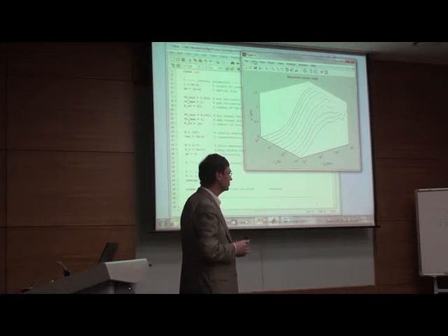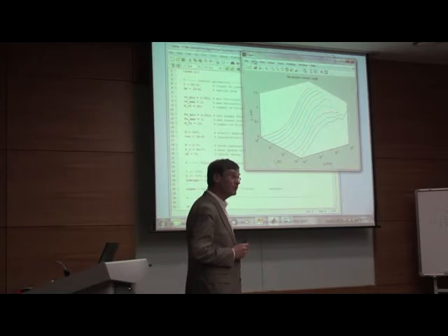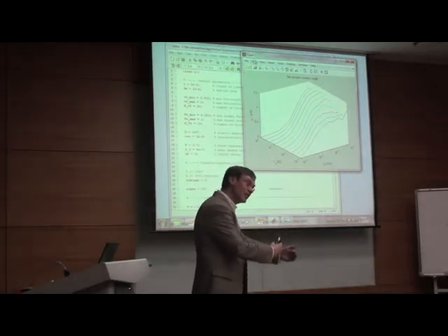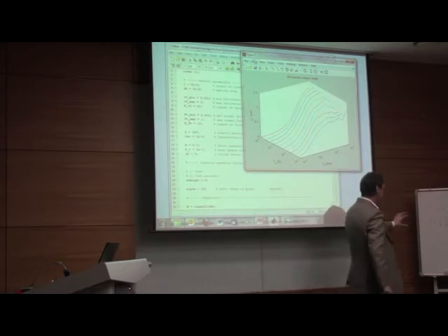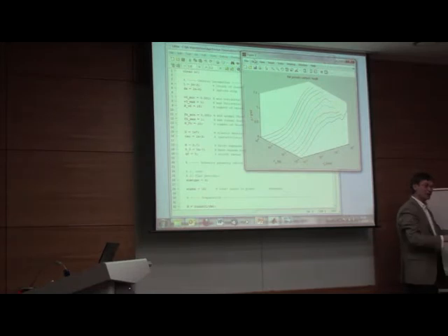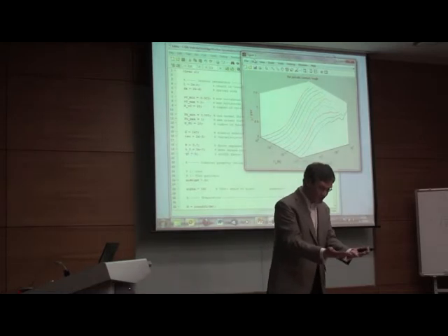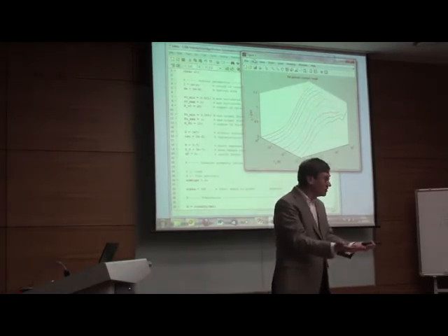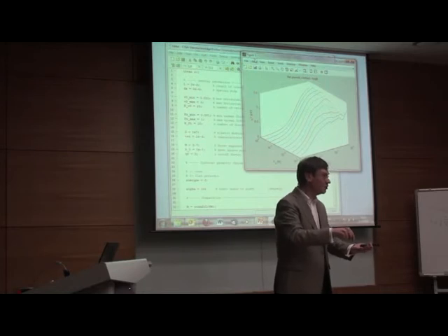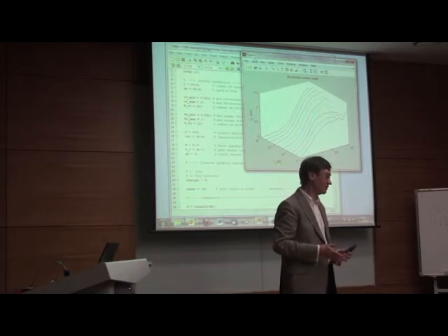Now, it seems to be a constant in your case, yes? No, it depends on the smaller scale. This part depends mainly on the largest wave, and this part depends mainly on the smallest wave. And of course, it depends on how small scales you take. So you can have completely similar surfaces, but they will have different frictional behavior because the smallest wavelength, which you do not see, is different, but it determines the friction coefficient.